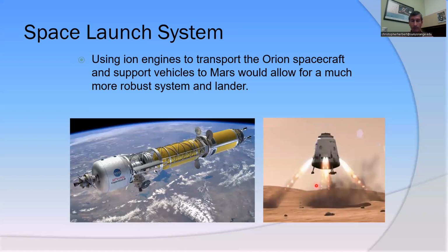But just doing the numbers, an ion engine makes more sense to get human beings to Mars than the current bipropellant rockets that we have. Here's the other problem that we run into with the ion engines. I'm painting the ion engines like, again, they're going to cure all our problems. We can't use the ion engines with the amount of thrust that they produce right now and solar panels to get us to Mars using Hohmann transfer, which those previous numbers are really utilizing.